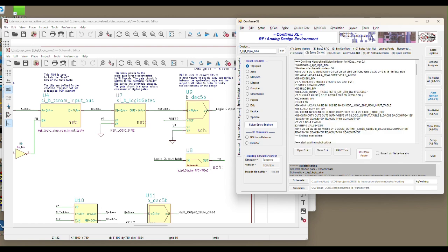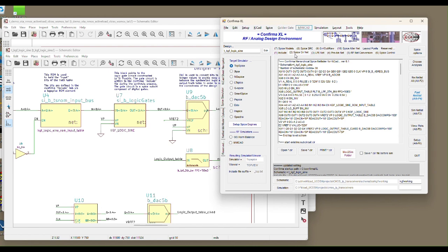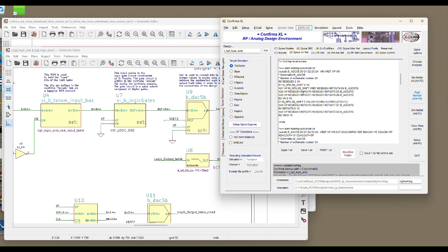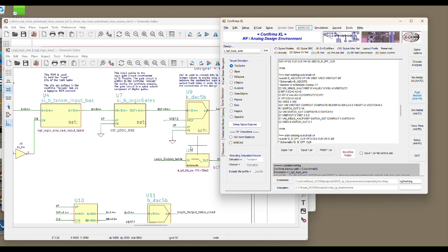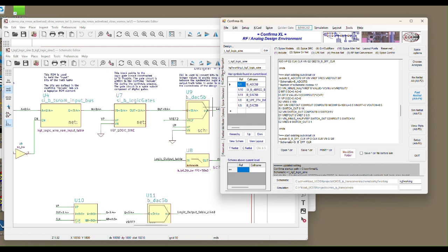If you look at the schematic netlist, the netlist that was extracted from schematic, this might be old, so I'm going to refresh this. So we'll refresh that. That was pretty fast. So all this SPICE net listing comes from this schematic system here. In fact, let's take a look at what's on there. So let me just regenerate the hierarchy. So it's already got the hierarchy here. So you can see there's a variety of hierarchical symbols with underlying schematics.